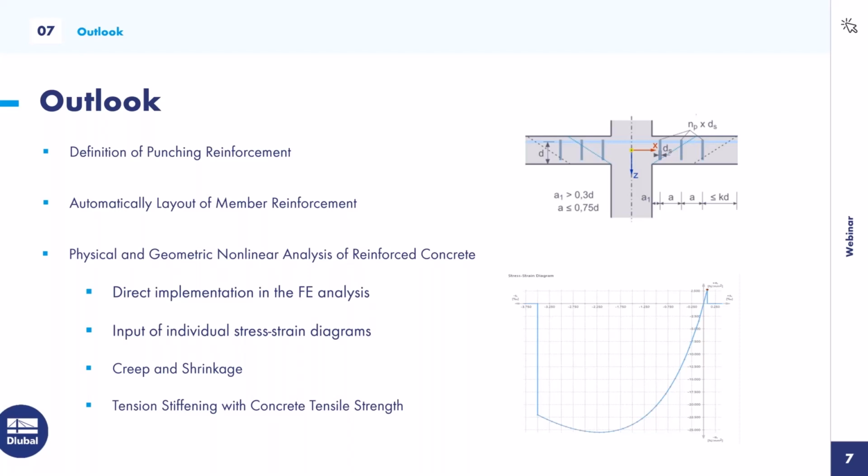So it is possible to use the nonlinearity of the reinforced concrete together with other nonlinear materials, or for example other add-ons like the nonlinear pushover analysis and so on.